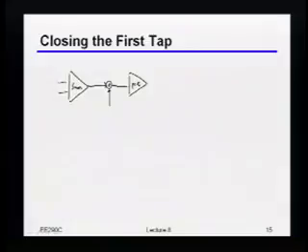To highlight why that is, let's draw a little block diagram of what this thing looks like. So the DFE, I usually go into some summing amplifier. Then again, in the current domain, I'm going to subtract off whatever that ISI is. I will still tend to go through a preamp before I go into the comparator.